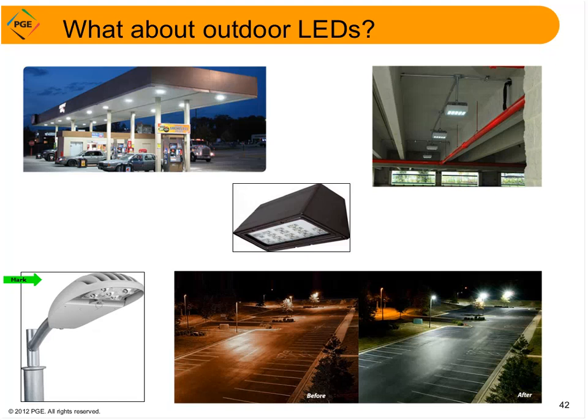Some people are choosing induction lighting for these applications, but I feel that it's better to wait for LED prices to come down in the near future rather than go with a short-term solution like induction. But in some applications, induction can be a good choice. In general, LED outdoor lighting provides more even light distribution, long lamp life, and energy savings of 50% and often more, and they work very well with controls.